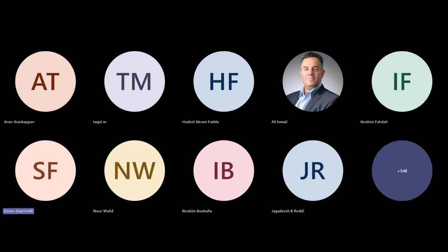For specialized buildings, it is required to submit a BIM model. The height applies, though I doubt very seriously that the height of a hospital or a school will be above 20 or even 30 floors, but the area might apply. The question is only architectural model or also the structural model for such buildings? Since they are specialized, if the area is above 30,000 square meters, then the structural model is required.